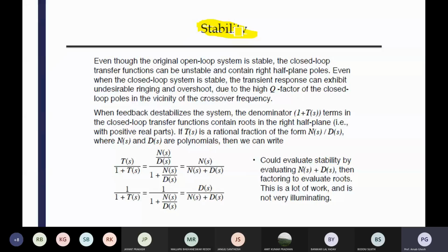There are different methods in switching converters for checking their stability. You know the root locus plot that I told you about. If you have the transfer function of your system, you can directly draw the transient response, meaning the step response, then you can plot the root locus. Then you can also go for the frequency domain. So different methods can be implemented, like your basic control system ideas, but you have to specify your system as LTI, a linear time invariant system. That is some consideration you have to think about.